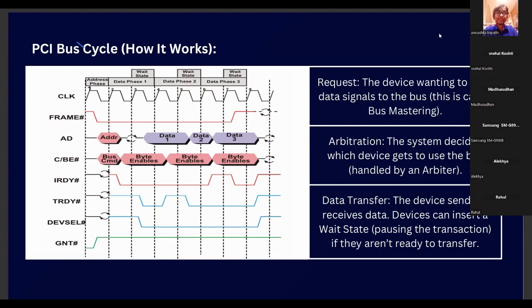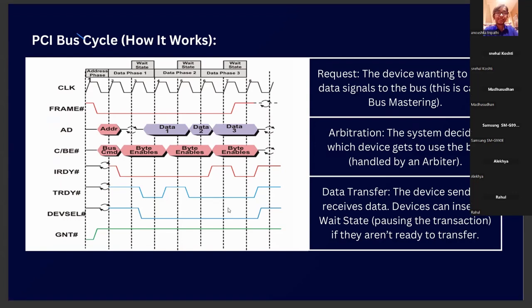I'm talking about PCI, not PCIe. So the other peripheral will wait for its turn. Once this is done, then it will select the second device. You cannot do multiple transactions in one go in PCI.